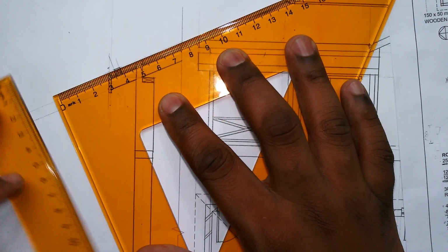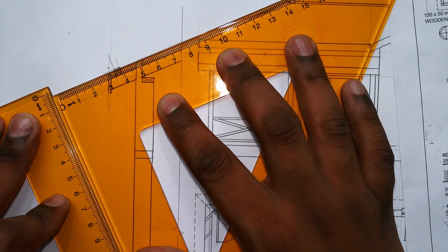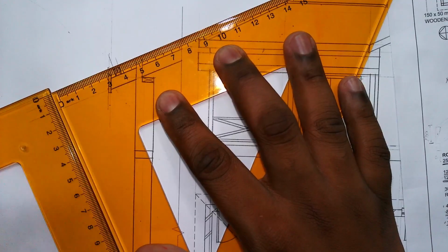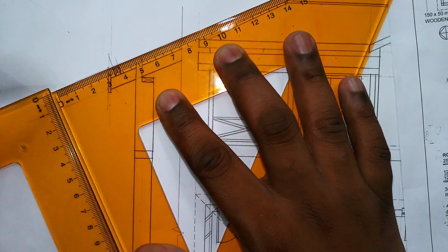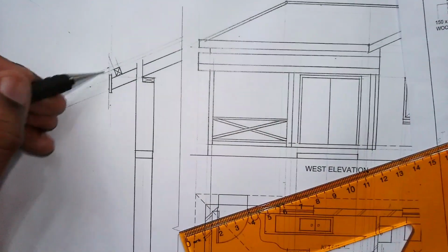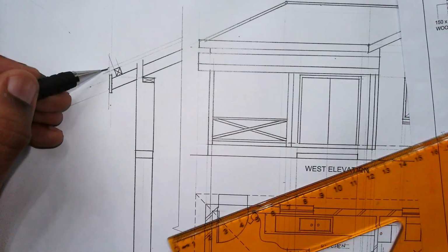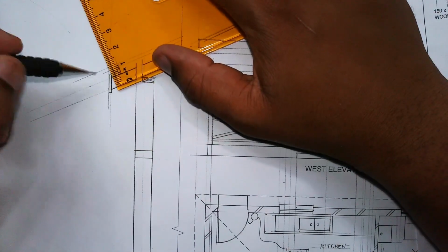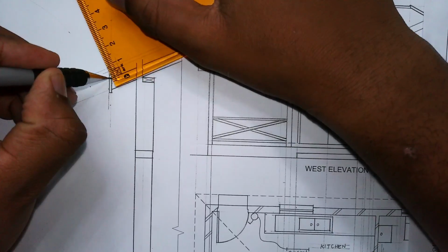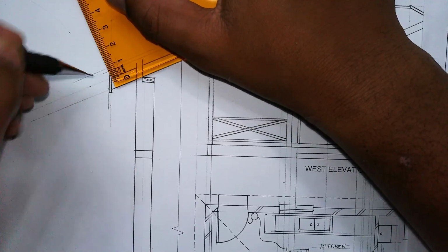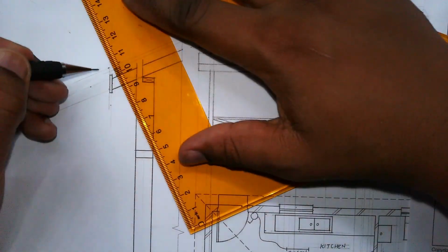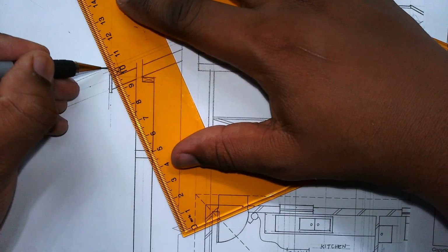All right, and then put the other set square next to it, and then slide to the point somewhere up there, and then I'll just draw a light construction line. So this is the thickness of the roof sheet. Okay, so now the question is, where does the roof sheet start? So what you need to do is, you see this point of the roof truss, I'll just draw a perpendicular line from that point. So I'll just draw a light construction line going up there. Then that means the roof sheet will start right there.